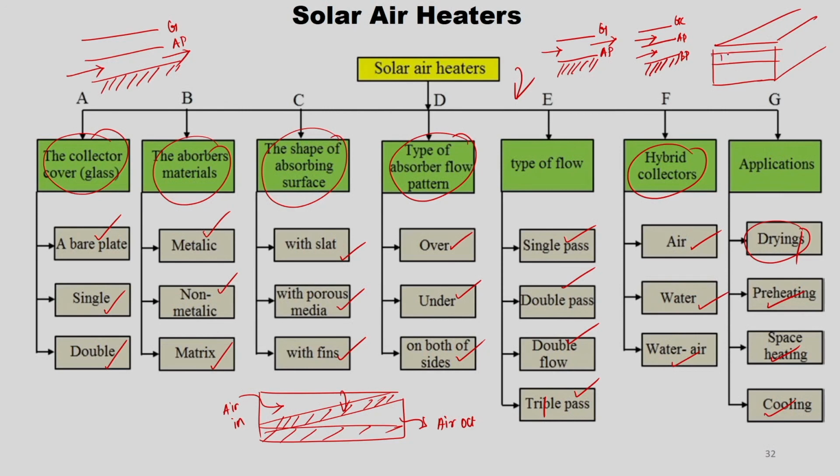So, you can have fins over here in the absorber plate, so that your heat transfer is enhanced. Or instead of this type of absorber plate, you have a glass cover and you have a bottom plate where your insulation starts. So, instead of a flat absorber plate, you can have this corrugated type of absorber plate as well. So, there are different designs, various shapes. You are requested to follow Sukhatme and Nayak's Solar Energy Engineering book for further details on solar air heaters.